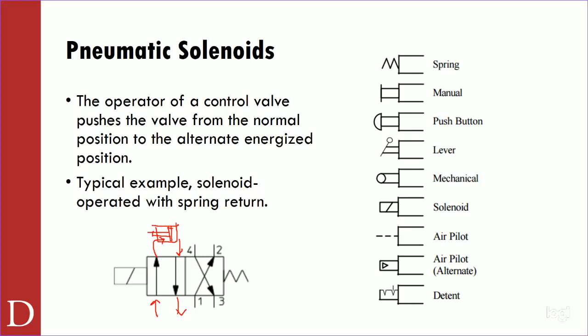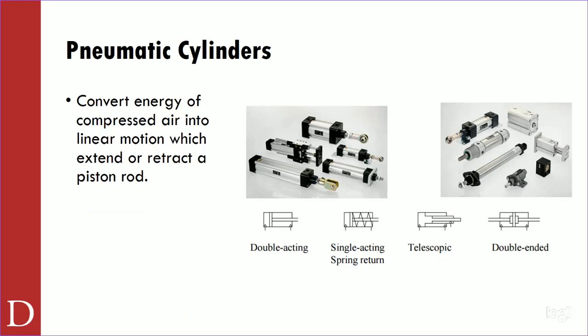It's like someone's holding an air hose with 120, well, it won't be 120 psi. It's whatever it's regulated to back there. It could be 20 psi just spraying out constant, right? But those mufflers will actually muffle that noise, and they'll exhaust that into the atmosphere. And the atmosphere, again, becomes our tank from which we do all of this work, right?